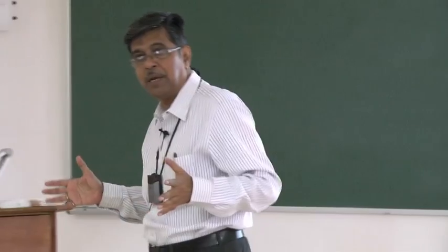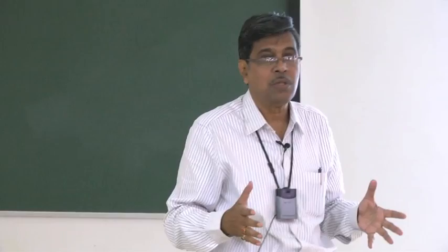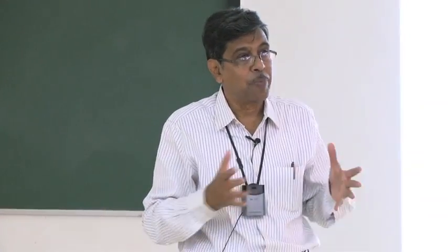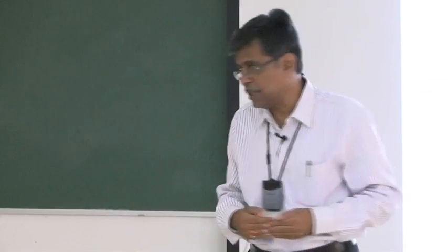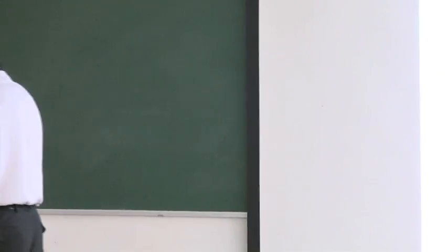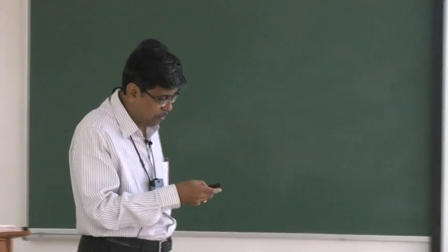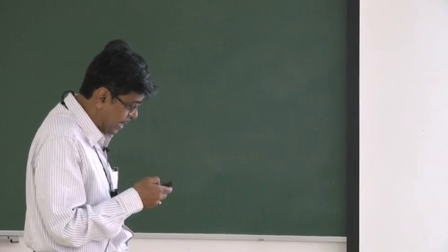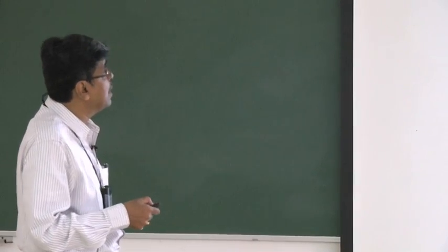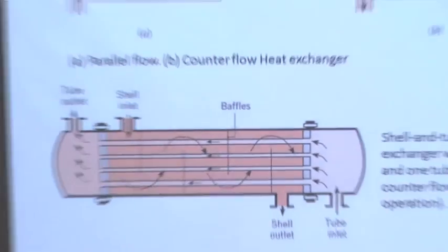This is for your information, but what we will learn mostly, that is used in industry, is the recuperator type of heat exchanger with indirect contact. That means heat transfer takes place between hot and cold fluid via a solid partition. Now I show you the most simple type of heat exchanger, like this, a concentric tube heat exchanger. This is the most simple type we can conceive, that there are two concentric pipes,